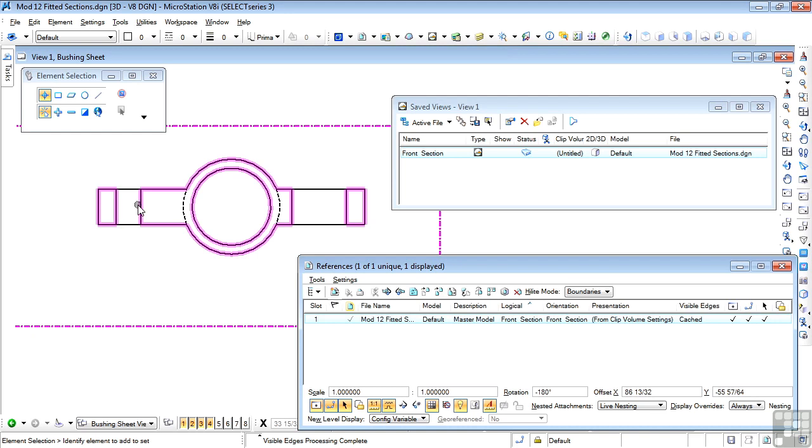These lines here, and here should be solid because that's the cut edges of those two slots. And we're seeing now correct hidden lines for this section. So this is a better method than the previous one. And of course, you notice that our tangent lines have also disappeared. Plus, of course, this method allows you to place sections very quickly and change the location of the section plane and display more of the object or not. So that works out very well.